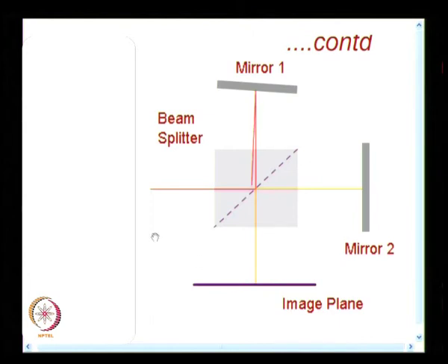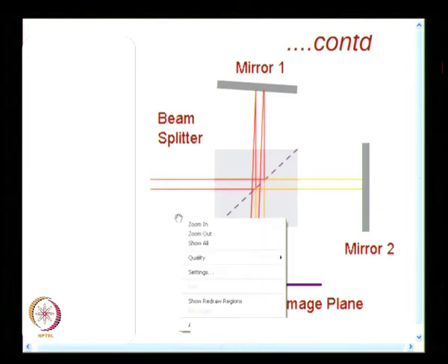And in shearography the vibration isolation requirements are less stringent, that is why it has become a very popular technique in industry, and many manufacturers are giving out shearographic equipment. It is used routinely for non-destructive testing of several composite panels, honeycomb panels and so on.